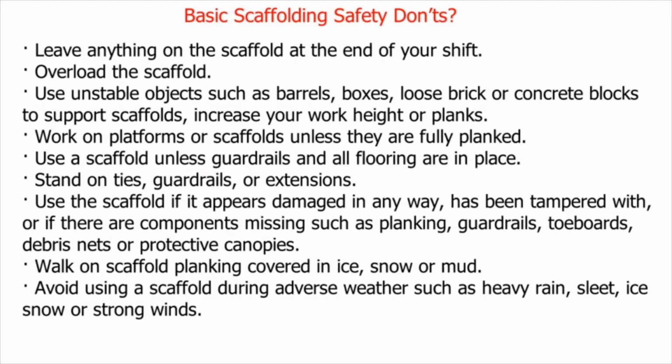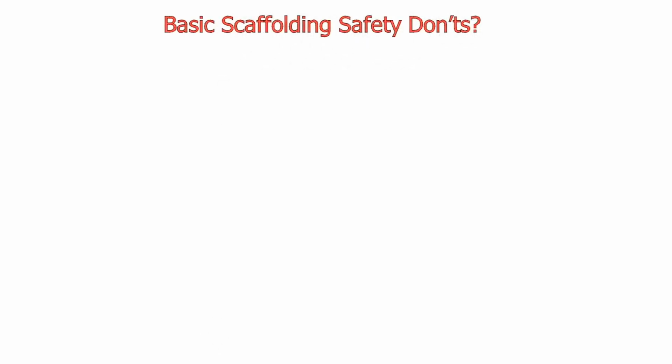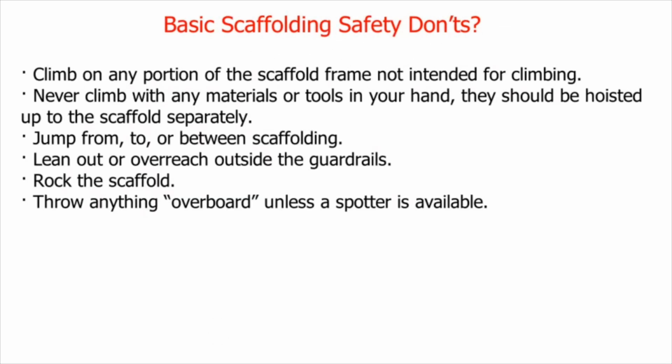Walk on scaffold planking covered in ice, snow or mud. Avoid using a scaffold during adverse weather such as heavy rain, sleet, ice, snow or strong winds. Climb on any portion of the scaffold frame not intended for climbing. Never climb with any materials or tools in your hand, they should be hoisted up to the scaffold separately.